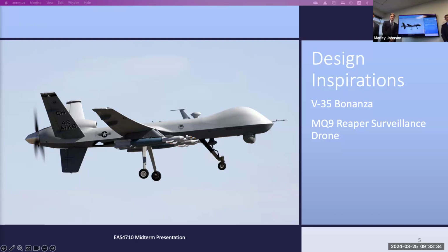Thank you. So that's one thing, this whole CG thing. It would be very, very helpful to show on your CAD model, like you showed us your model, where's the CG, where's your believed aerodynamic center and stuff like that. That way, we can see you guys have that in mind. Just because when you show it to us, we have no idea where you're placing stuff. It would also be helpful to show, okay, the battery's going here, these are camera components. Or in this case, if you don't have those components at the moment, you place them in as weights and say that as well. Motor in the back. That way you get a nice CG estimate just by looking.